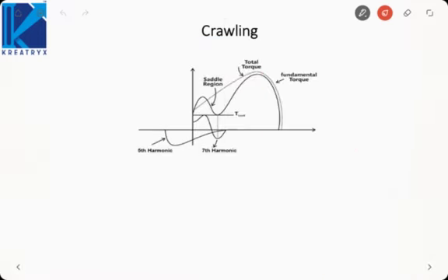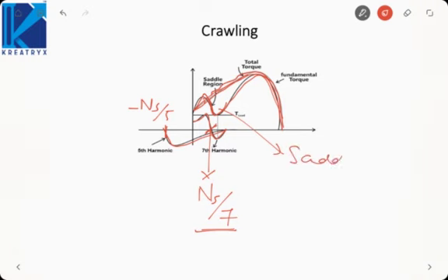So what happens? This is the torque slip characteristics of the fundamental. This is the torque slip characteristics of the seventh harmonic. This speed here is ns by 7. And if you see, the torque slip characteristic of the fifth harmonic is reversed because it is a negative sequence field. So this speed here is ns by 5 in the negative direction. Now if we add these torques, the net torque looks something like this. So there is this saddle region formed. This is called the saddle region.